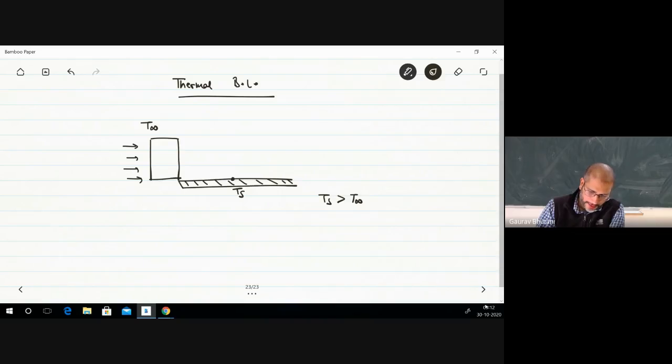What we see is that on the left hand side we have this T infinity. I use these lines in the x direction to denote the extent of the temperature. The longer the lines, the larger the temperature value. So just before the flow impacts the flat plate, the whole fluid is at T infinity temperature. But when the fluid impacts the flat plate, you see that again a boundary layer develops, but in this case, we're talking about the boundary layer of temperature. The boundary layer, anyways, is a hypothetical concept.